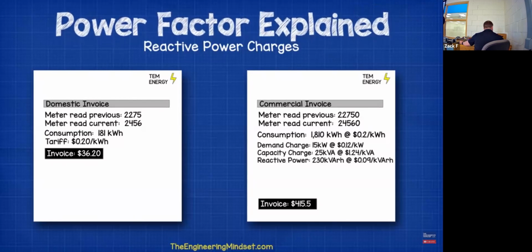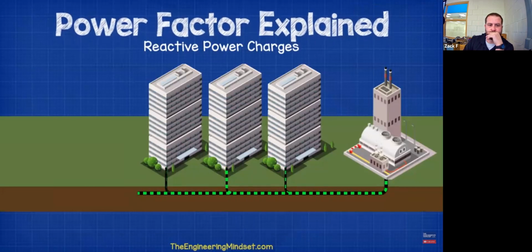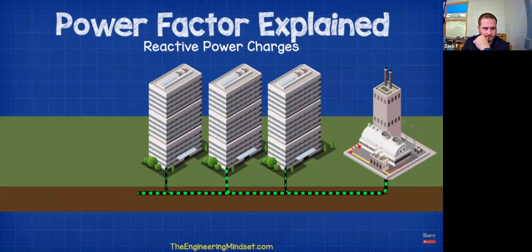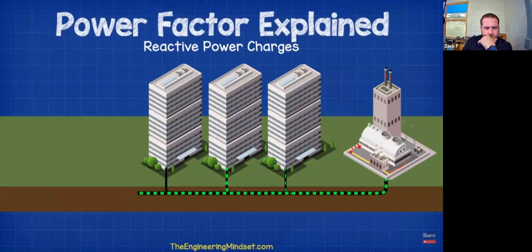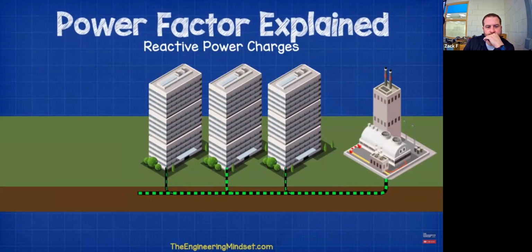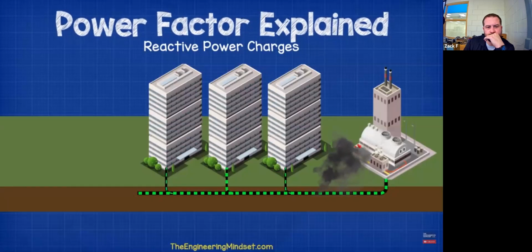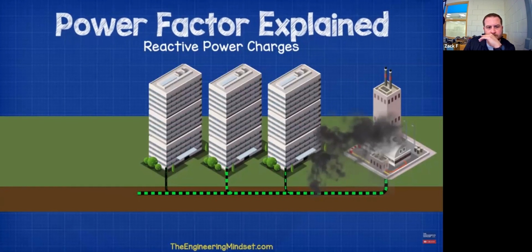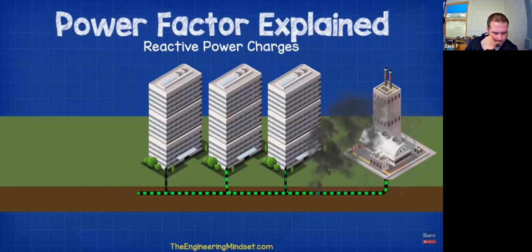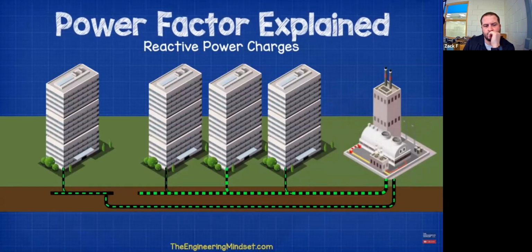The reason they charge a penalty for this is because when large consumers have bad power factors, they are increasing the current flow through the electricity network and causing voltage drops, which reduces the supplier's distribution capacity and has a knock-on effect to the other customers. Cables are rated to handle a certain amount of current flowing through them. So if a lot of large consumers connect with bad power factor, then the cables could overload. They could also struggle to meet the demand and the capacity agreements, and then no new customers will be able to connect until they either replace the cables or install additional cables.